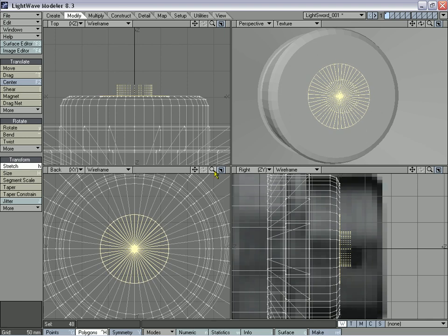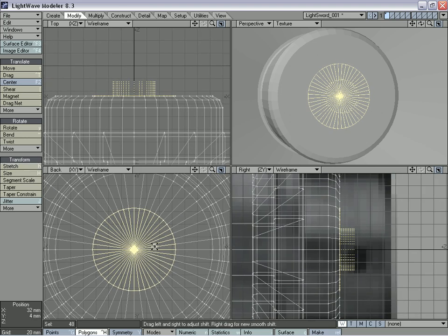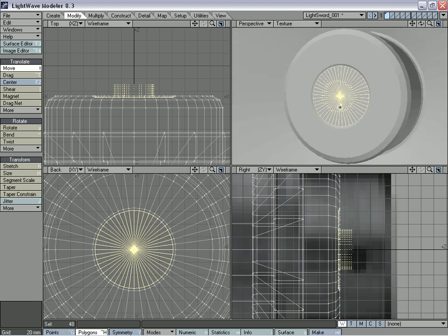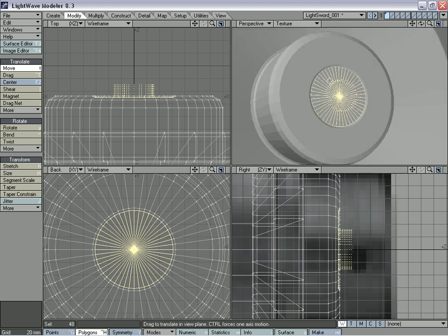And we're going to go ahead, and that looks good, and smooth shift again. So Shift F and then right mouse click, H for stretch, and stretch that in again, constraining. And now we're going to hit T on the keyboard and move it in just a little. And we want to work our way into this curve.